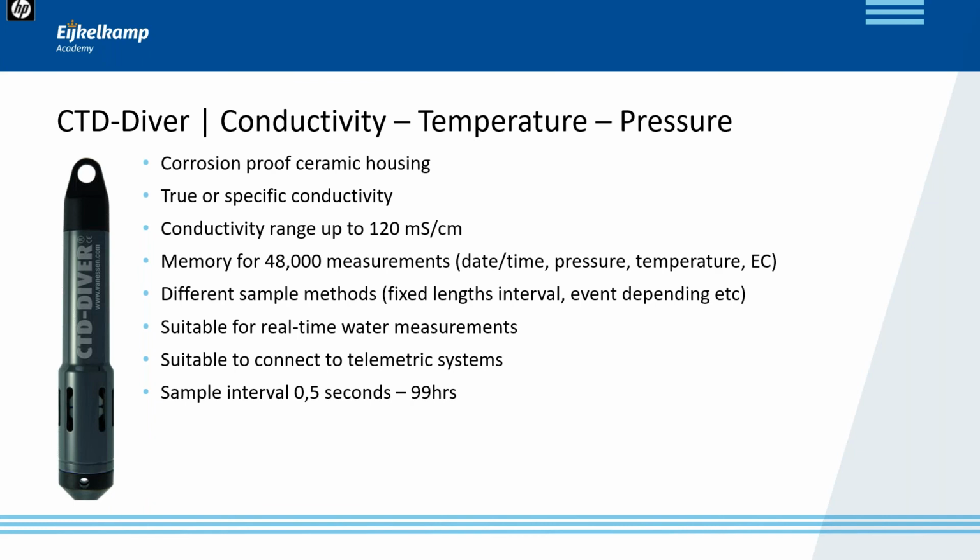The CTD-Diver is a submersible data logger for long-term, uninterrupted or real-time water level monitoring using a pressure sensor submerged under the water surface. The pressure sensor measures the hydrostatic pressure of the water above the sensor to calculate the total water depth.